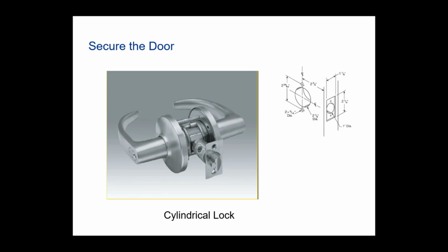One manufacturer that comes to mind is Krieger, where they have an extra panel onto the face of the existing panel. By doing that, you have to have some sort of special casing, the gasket and things like that. And because of that, you have to have an extra deep latch. Could be 5 inches, could be 3 3/4 of an inch. Just depends on what door you're using.